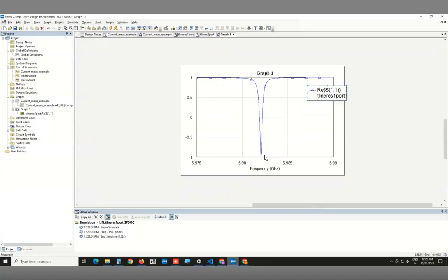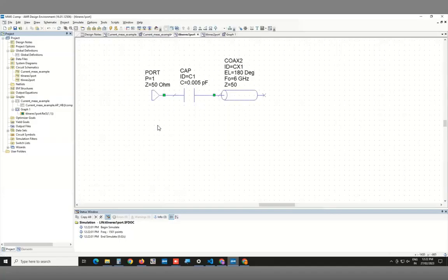If you remember, some of you remember the measurements from just the LC oscillator, the parallel LC oscillator, it goes from -1 to +1. It's inverted. This inversion happens because of this coupling capacitor. That gives you a 180-degree phase shift, so it flips the whole thing, but that's not really a problem.